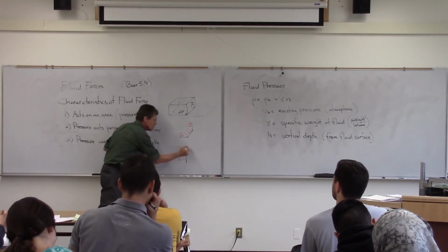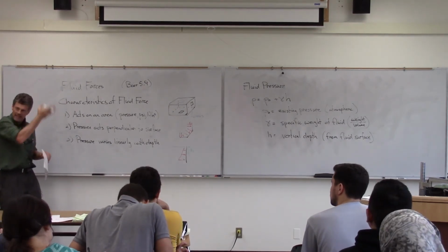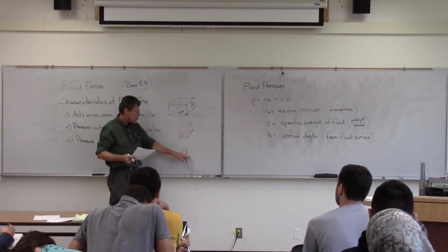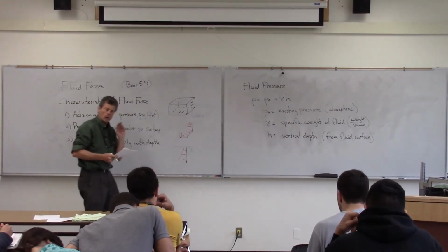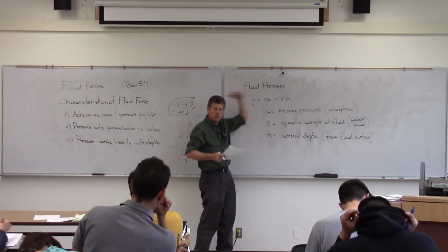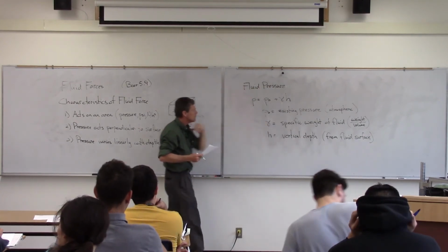This h is a little bit different. So the positive quantity for h is going to be down. So in terms of however I set up my coordinate system, h is always measured from the surface going down, basically. So as we can see, it's just collecting the weight of this water as we keep going further and further down, this weight of water that's acting on us, and increases that.